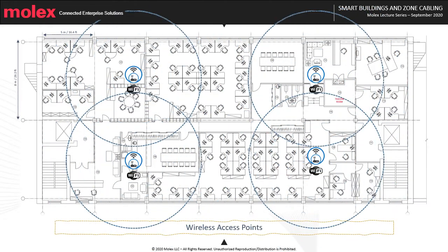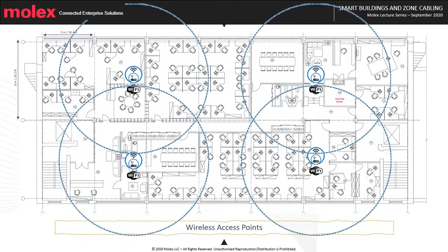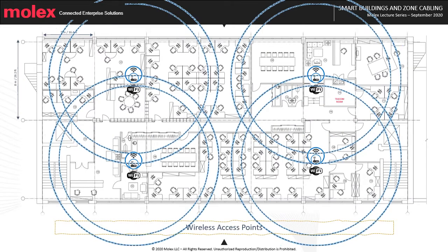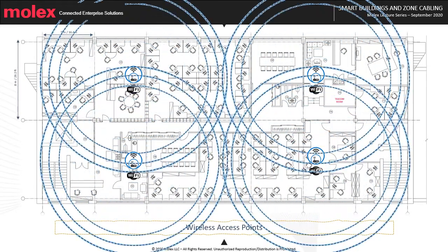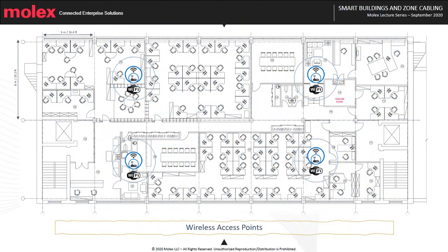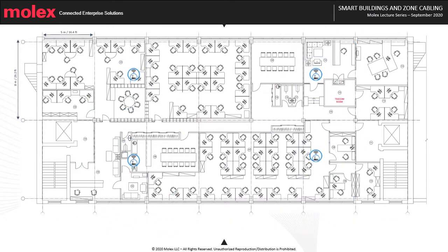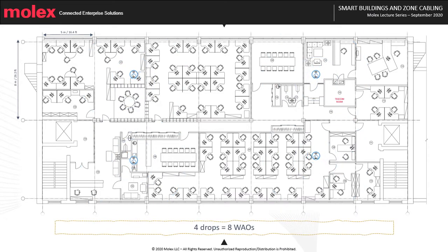The grids may be smaller as well to allow for higher data rates or support increased occupancy. Category 6A cabling is deployed to each WAP for higher data rates and increased power delivery. As per international cabling standards, for wireless access points and intelligent buildings, Category 6A is recommended. The use of 2 horizontal links per WAP is also recommended to allow link aggregation.